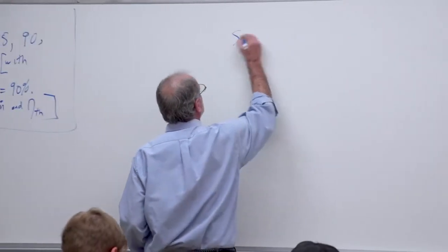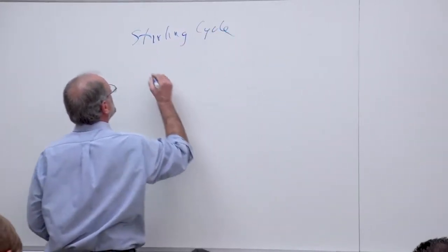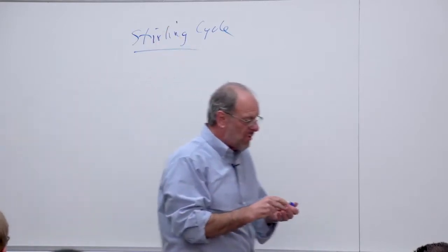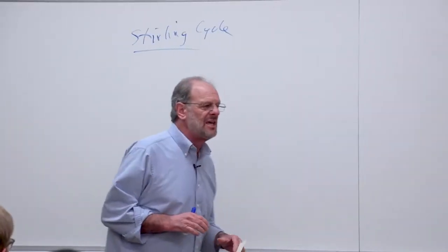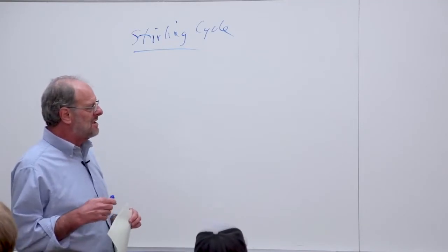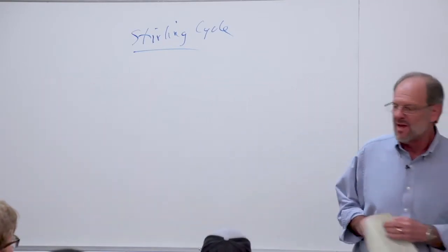So we'll just start with the Stirling. And quite frankly, I probably shouldn't call it engine at this point. I mean, granted, these are all heat engine cycles, so it's not incorrect to call it an engine, but we're really just talking about the thermodynamic cycles now. Now, the Stirling cycle, like the Ericsson cycle, are rather unique in that they're gas power cycles, yet the heat transfer takes place at constant temperature.